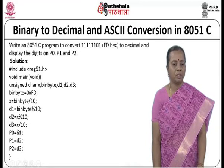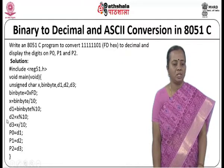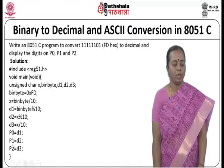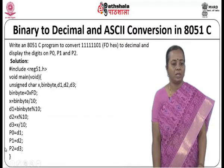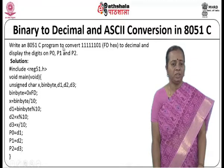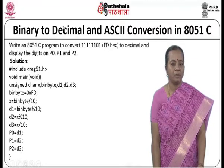Then for the third digit, x divided by 10 is your third digit. So, if I have a 3 digit number, it can be generated with this particular code. Now, D1, D2, D3 are the values which tell you the first digit, second digit and third digit. Now, I am moving the values to P0, P1 and P2, so that D1 is displayed at port 0, D2 at port 1 and D3 at port 2. So, you just see this code for binary to decimal conversion.